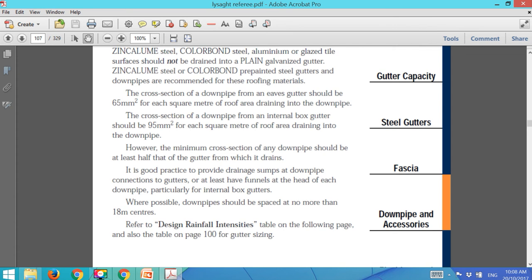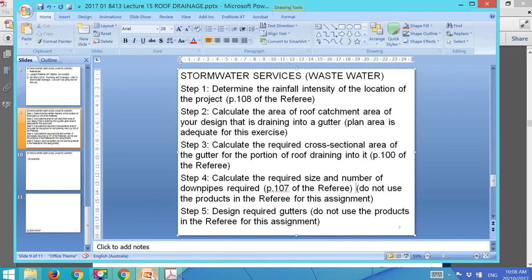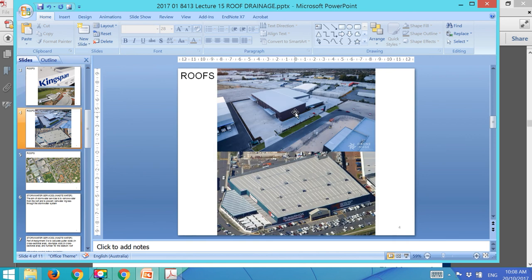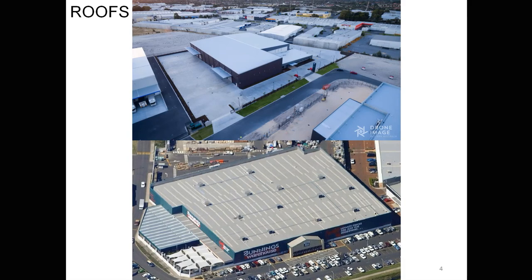There was actually a company that was doing siphonic downpipes. And what they could achieve with that kind of downpipe was really to have a roof as big as the one on this warehouse here, all draining into one downpipe. That's because they had a specific kind of box gutter, which forced the water into a spiral, and because the water was going in a certain direction, pretty much like a toilet, right? Because it was twisting in a certain direction, it sucked all the water out of it. So it's remarkable how little you need.